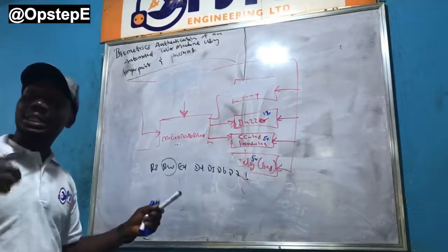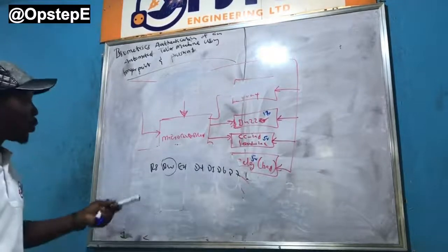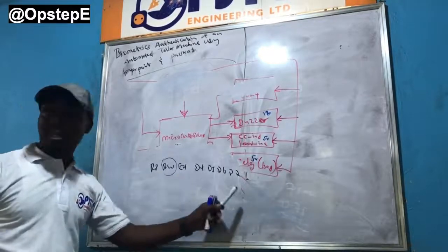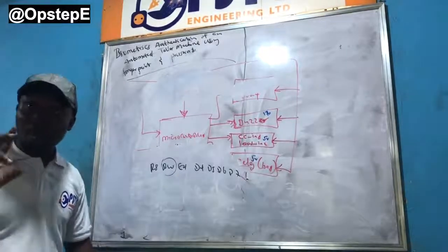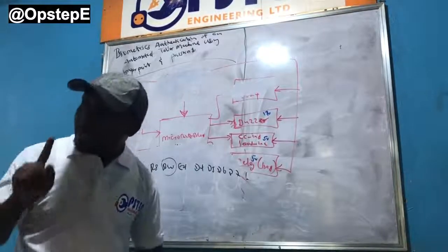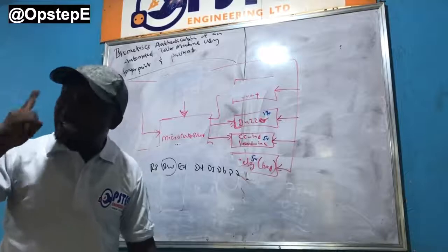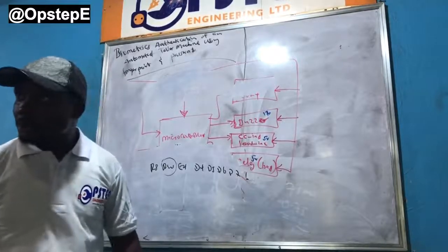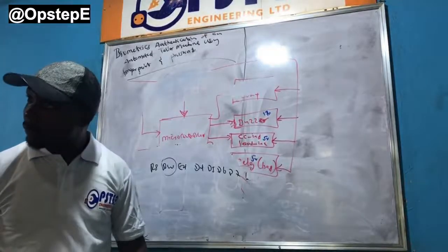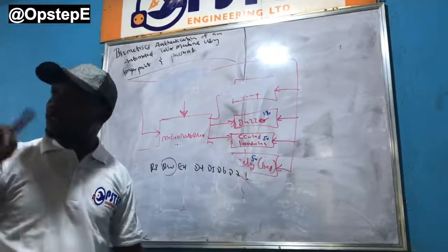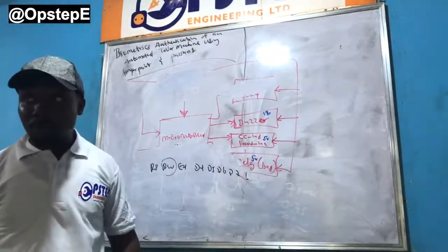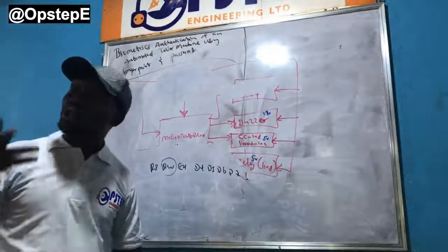My RW has been taken to ground. So what I'm left with is the RS, EN, D4, D5, D6, and D7 on port A. But understand this, which is key. On your port A, there's one pin that cannot be used as output. What pin is that? Your RA4. It's the same thing as your T0CKI, your timer clocking pin. It doesn't work well as output. Why? Because it's an open collector pin.